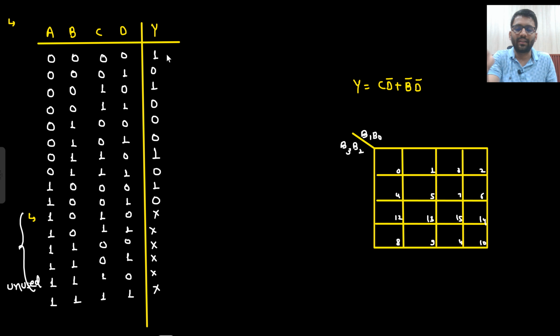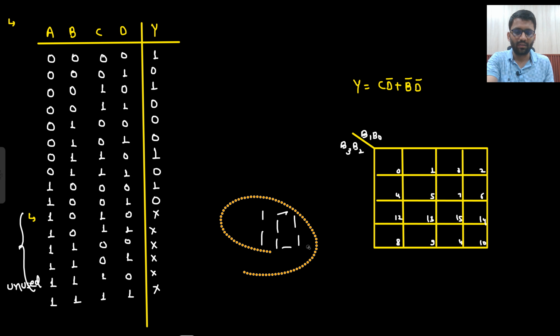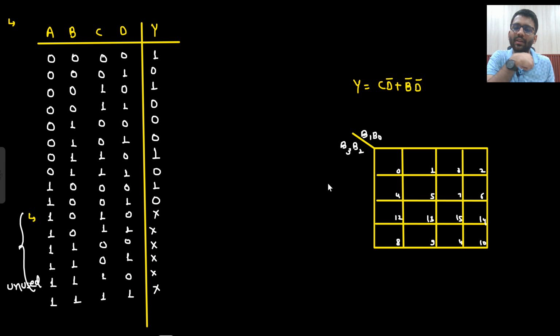Let's check again that I have written it correctly. 0, 1, 2 it will use, 3 it will not use, 4 it will not use, 5 it will not use, 6 it will use, 7 not use, 8 use, 9 not used, and then all these are don't care. It's not that you will write 10. Now 4-bit input is there, so all these are don't care. 4-bit BCD. Okay, so what all are the minterms?